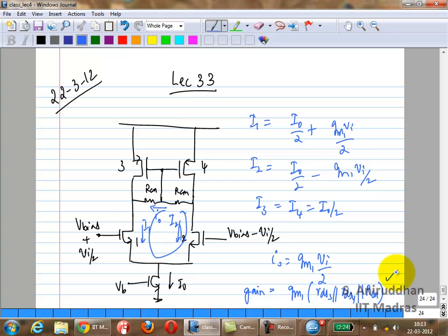We'll go ahead with this first, but this is a point to be noted, because you ideally want your common mode detector to have infinite input impedance, so it won't affect DC gain at all. Why is that? We started off with a single stage differential op-amp, so you cannot afford to give up on DC gain, just like the case with a single ended op-amp.